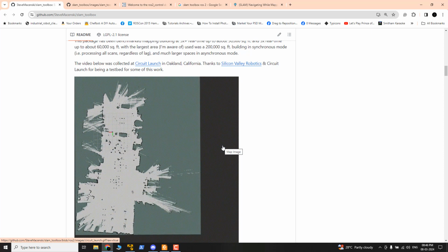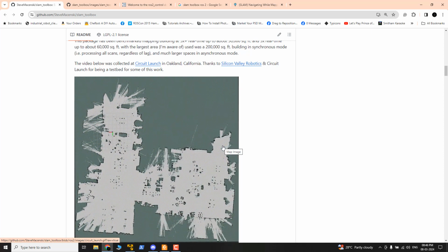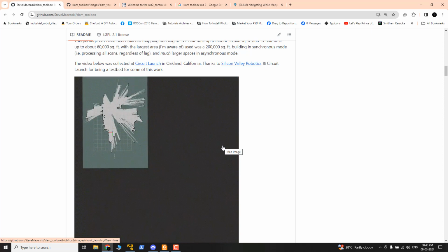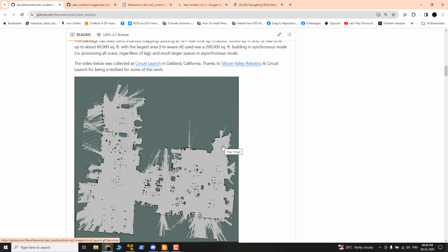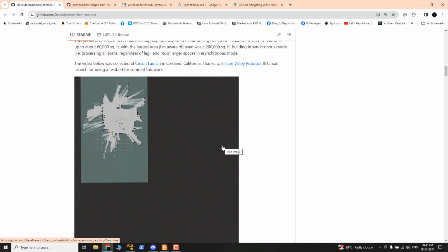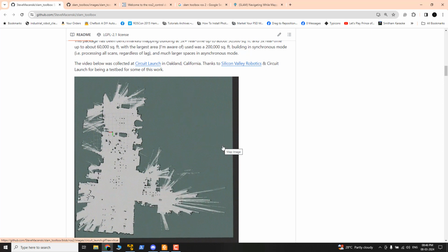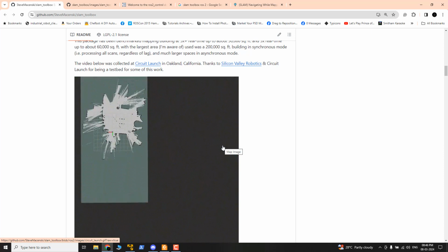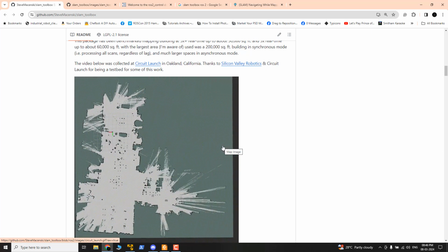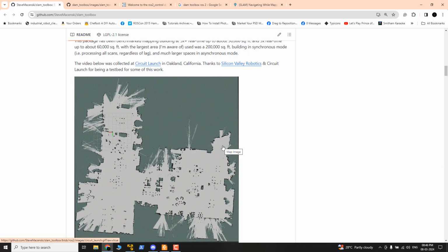Okay, so there are a few SLAM algorithms in ROS supporting loop closure. If you take Hector SLAM, it does not have loop closure, but Gmapping has loop closure, and Cartographer is what is used in the SLAM toolbox. There are a lot of improvements in it, and not only the loop closure.